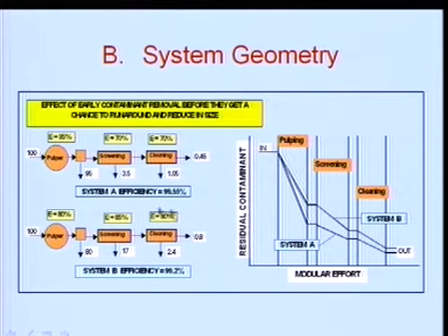You do the same system in which you say 80% efficiency in the pulper. Somebody decided to put in larger holes or whatever, and because more contamination is going to screening and cleaning, you can generally say we have higher efficiency in the screens and the cleaners. As you can see, we've got 80 and 80 here. However, the overall efficiency of the system is less than system A, which shows you that early decontamination is more effective than later decontamination.